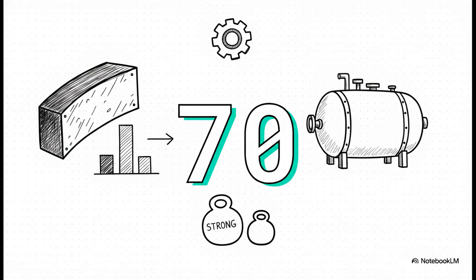Now, these numbers aren't just arbitrary placeholders. They actually represent the material's minimum tensile strength. So a grade 60 plate has a minimum tensile strength starting around the 60,000 psi mark, which translates to a specific threshold in megapascals if you're using metric units. Grade 70, naturally, has a higher minimum tensile strength.